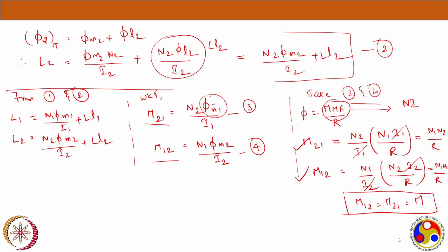leakage inductance. But while calculating the mutual inductance, leakage won't take any part, because mutual is between the main coils, and it is caused by the linkage of main flux with the opposite coils. So there is no concept of leakage in calculating the mutual inductance.